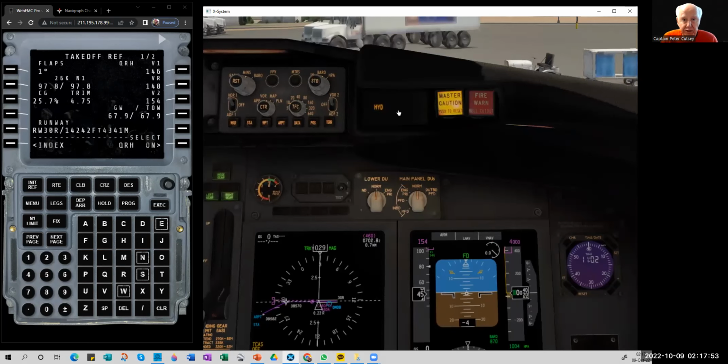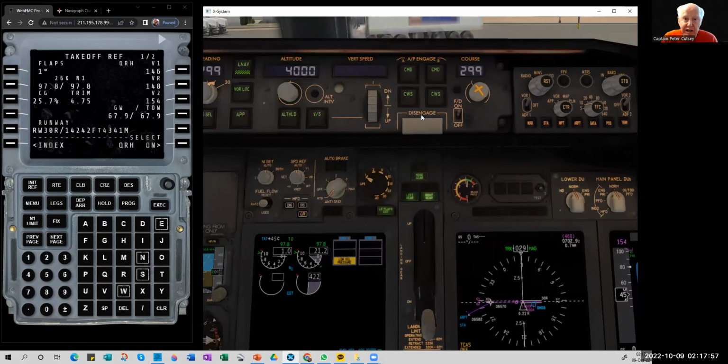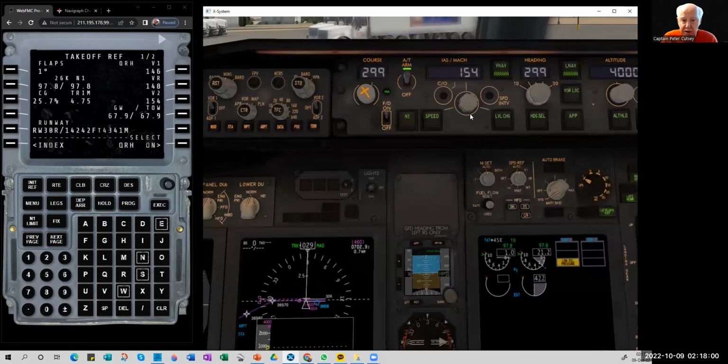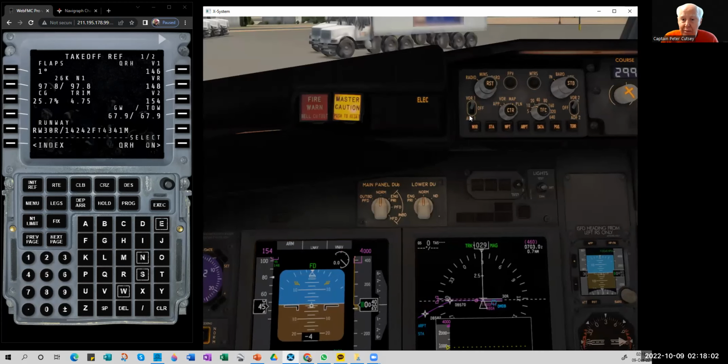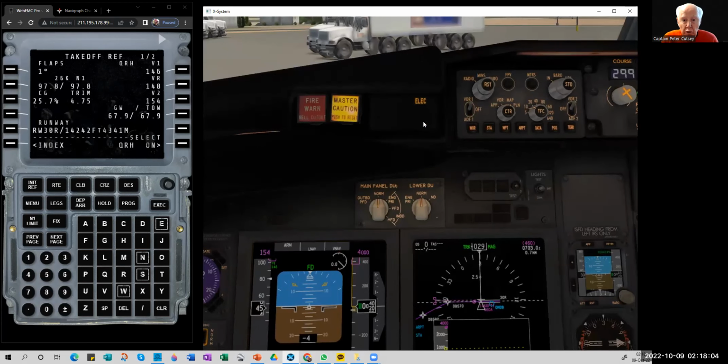But remember, the first officer's annunciator has 6 different system monitors or alerts as compared to the captain. So this is a combination of 2. So we would reset the master caution so that we would have it ready for anything else that came on. And then when we wanted to find out what the problems were, we could push the master recall.